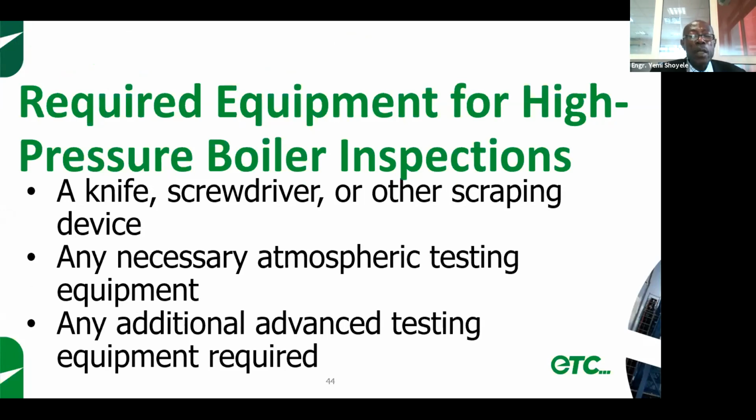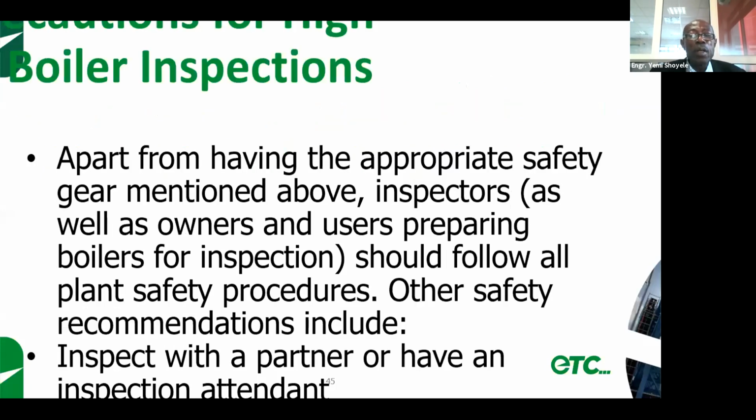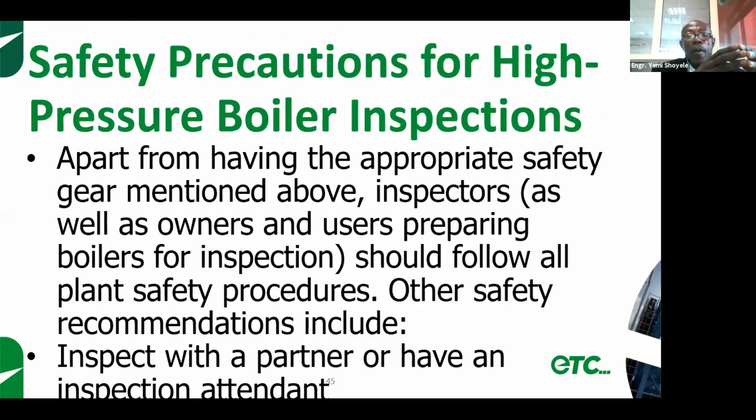Now, very importantly, any necessary atmospheric testing equipment. Before you ever venture into a boiler to work, or for anybody to go and work, you need to have the atmosphere tested, just in case you might have some dangerous gases still not properly vented. Carbon monoxide is a typical example, and it's not uncommon to have such issues, so that people don't go in there and faint. Okay, and then any additional advanced testing equipment that you may have.